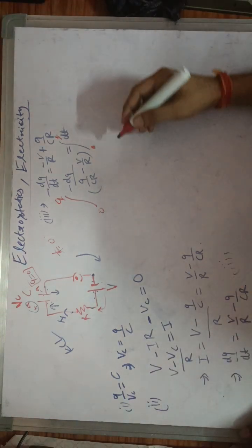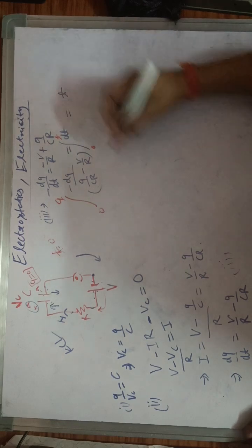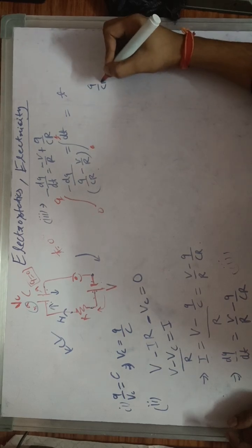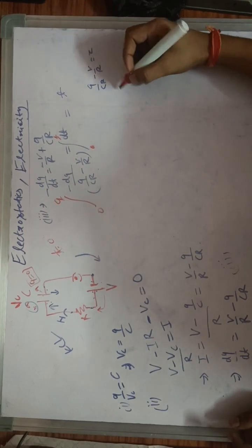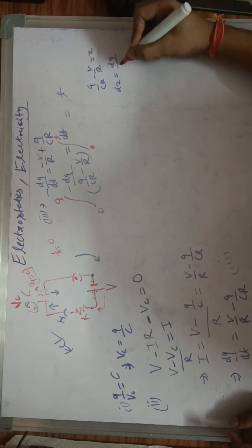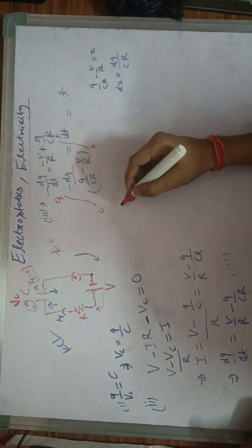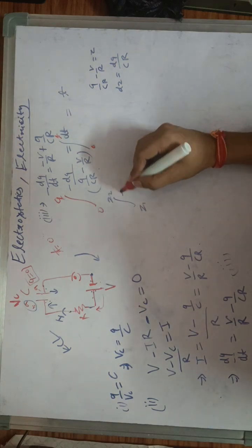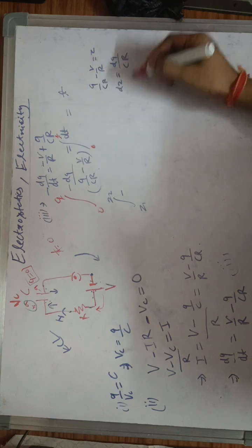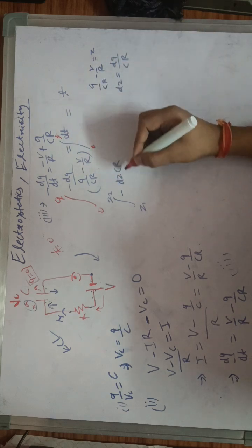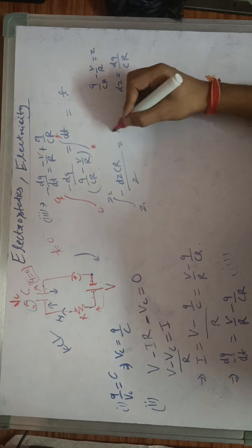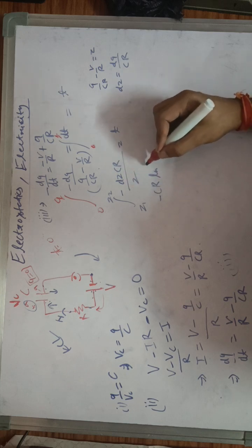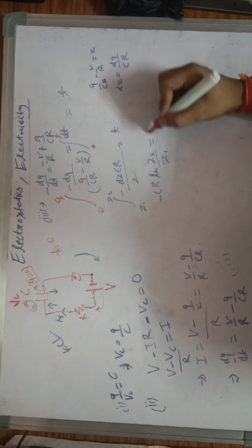Then in that case we will get t here, and let's say this whole value q by CR minus V by R is equal to z, then dz is equal to dq over CR. This gives this integration from z initial to z final minus dq is equal to dz and to CR divided by this z, that is equal to t. Now integration of this will give CR minus ln of z2 over z1 is equal to t.